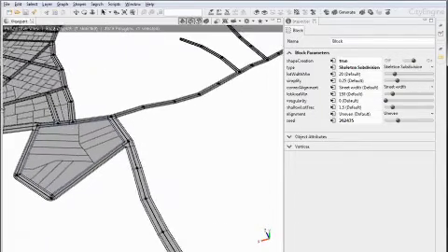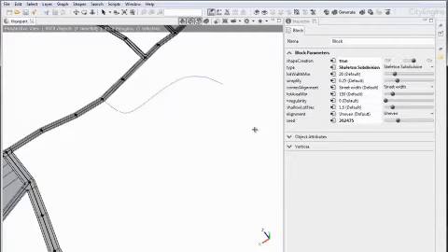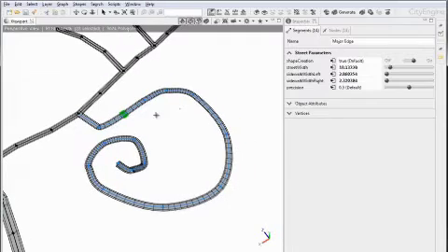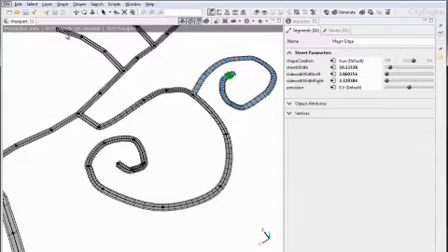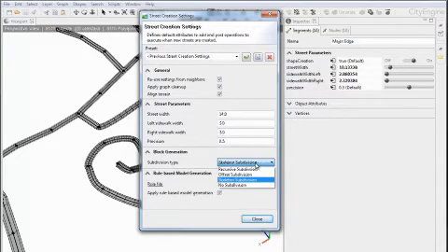Okay, let's talk a little bit more about the shape or the street creation. For this we have two specific tools. The one is the polygonal shape creation and the other one is the freehand street creation. So you can go in and just really paint some streets here and design your own city layouts that way. Now there are also settings for this under Graph, Street Creation Settings. There's this window where you can set all the default behavior, like the default street widths, and for example when blocks are generated you can choose the subdivision type and which rule should be applied.